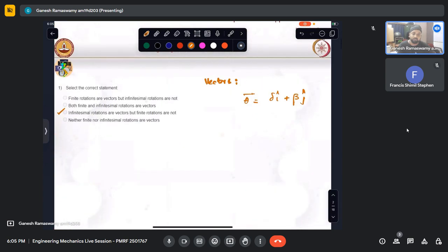So far in 2D kinematics, we have looked at a lot of examples, how to analyze absolute motion, and how to analyze motion using relative analysis. Basically, we take a rigid body, and we take one point whose velocity we can gauge, possibly some constraint point or the mass point. Then we look at another point and invoke our circular motion equations by virtue of r being constant because of the rigid body constraint.